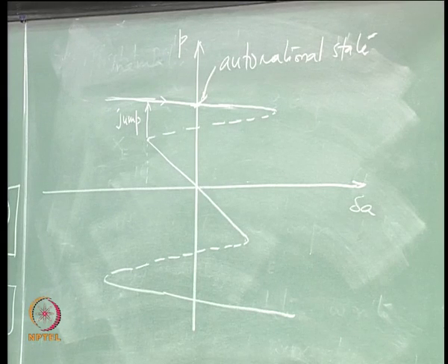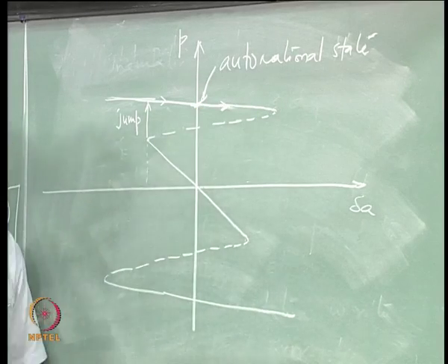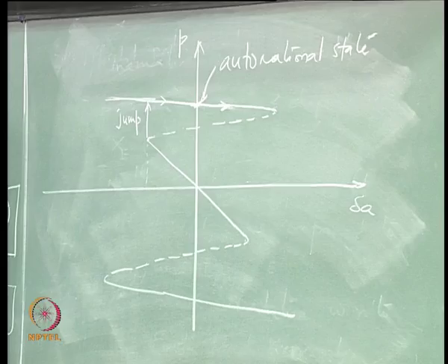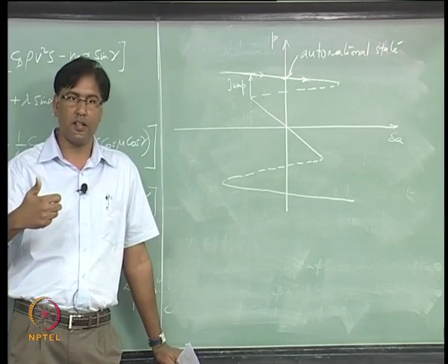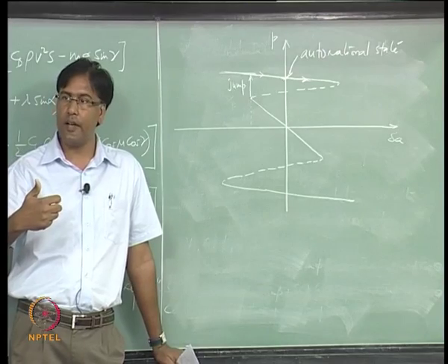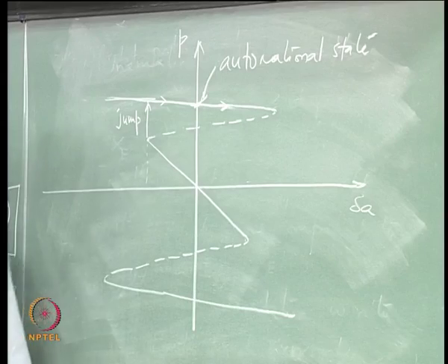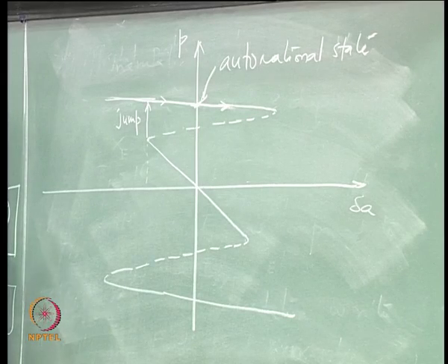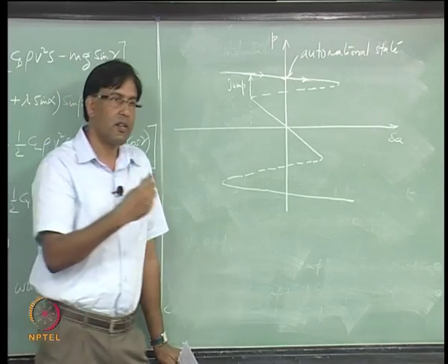So automatically the aircraft is rotating even without applying any control which can give you rotation. Further, when you further decrease aileron, or start changing the aileron in the opposite direction, you see still positive roll rate. This positive roll rate is for positive aileron deflection, right.